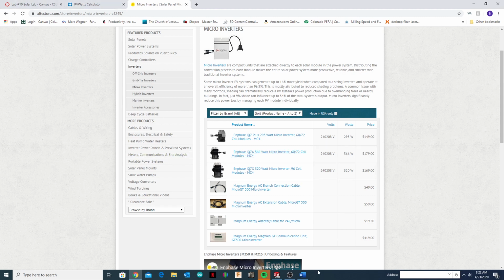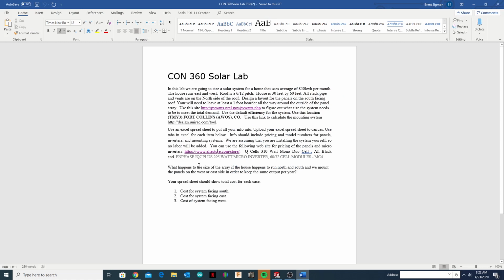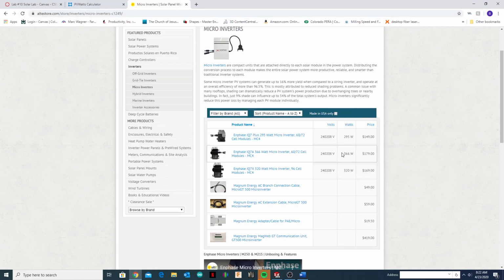What one did I have listed before? Let's go back here. I had the IQ7 Plus 295 watt one. Well, they have the new one. This is a new one that just came out for 366 watts. It's going to give us a little bit more power, especially since we're using a 345 watt panel. Okay. So again, use the Enphase IQ7A 366 watt.